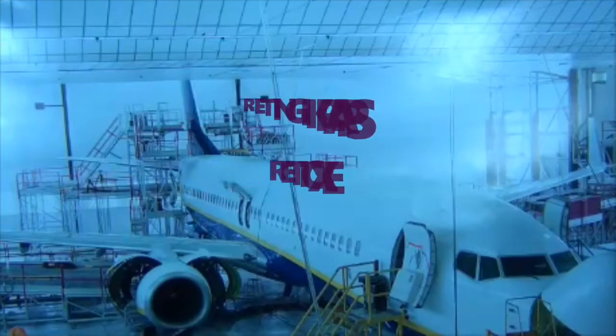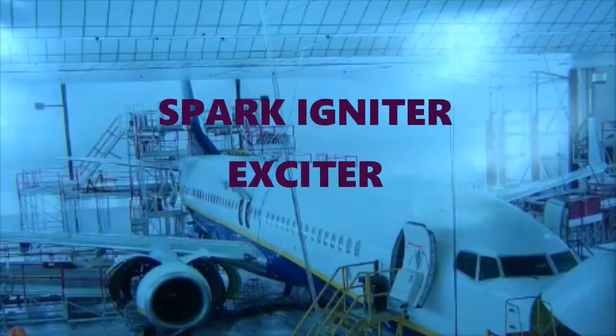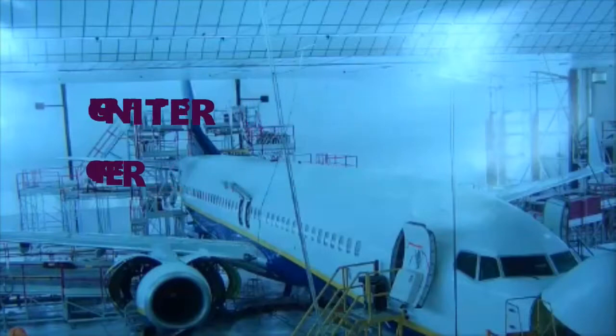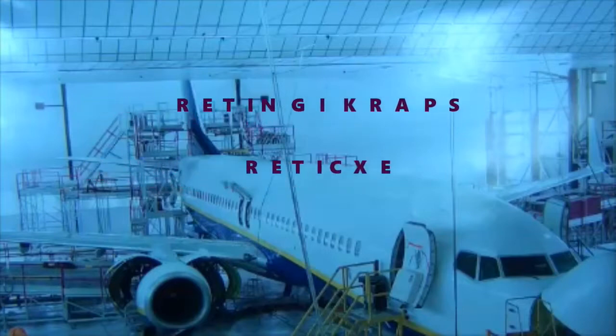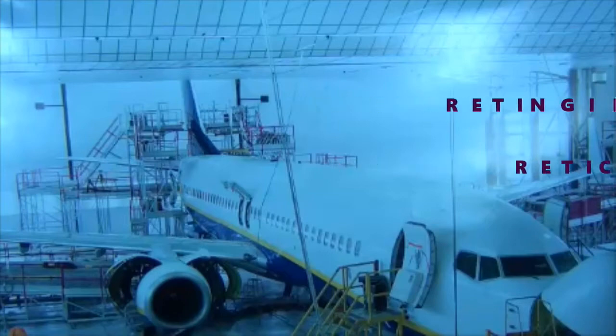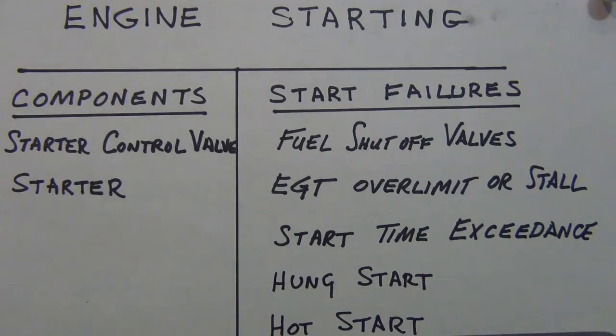Okay, so in general we have some of the smaller components that are part of the combustion: the spark igniter and the exciter. I mentioned this before with ignition: the exciters have a 115 volt power source, from which they transmit electrical pulses to the igniters, which are connected to the combustion chamber, and that all gets intermixed with the air fuel mixture in order for the combustion to occur and have that slow burning. So that's the process that we're talking about.